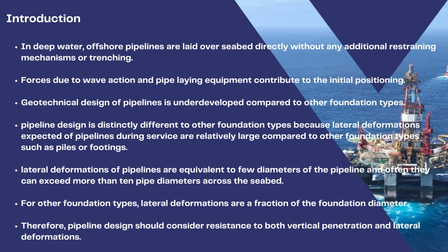Because in piles and shallow foundations, lateral deformations are normally a fraction of the foundation diameter, but in the case of pipelines, the lateral deformation can be more than 10 times the pipeline diameter. Because of that, pipeline design is not similar to the pile or shallow foundation design.